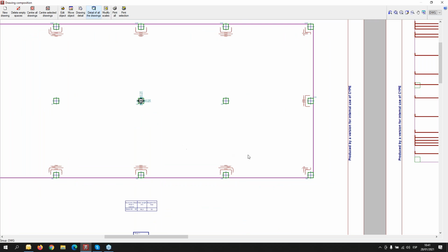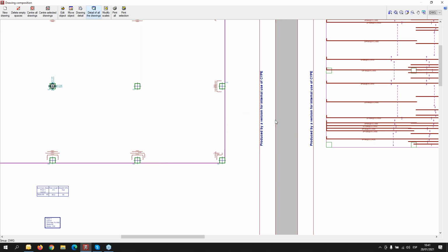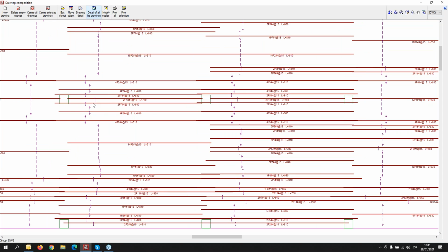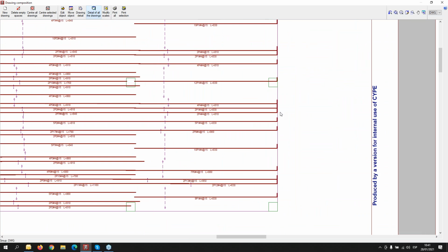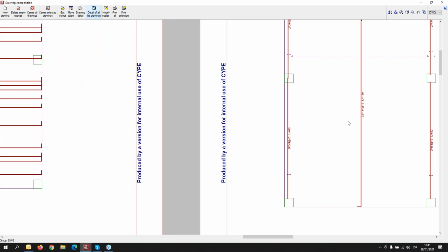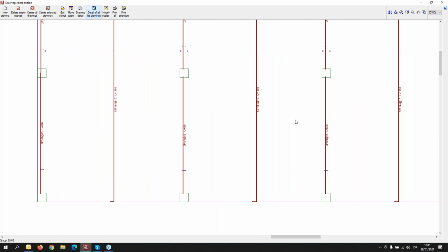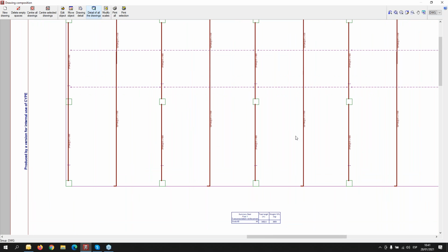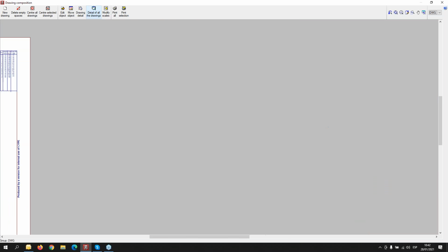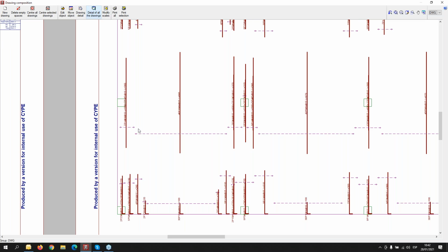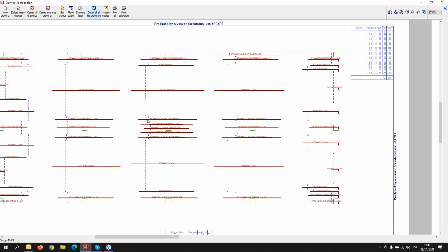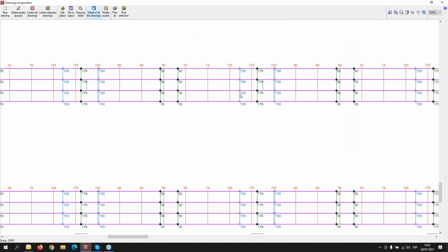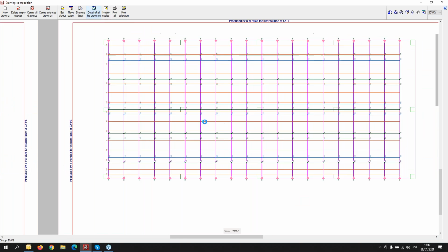So the reinforcement of the punching shear, the classical one, the longitudinal at the bottom of the slab, the reinforcement for the bottom of the slab, but this one, the transversal one, on the top, but longitudinal, and here the information of the tendons of post-tensioned elements.